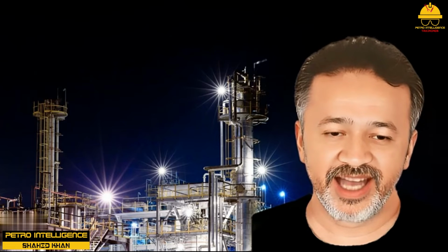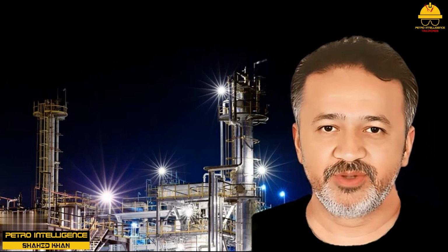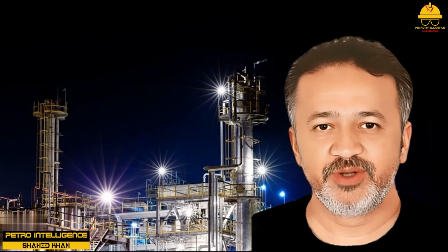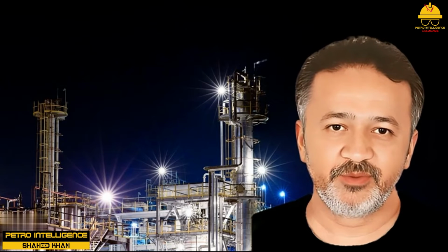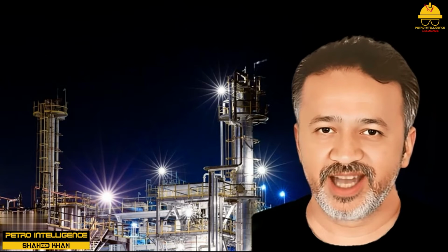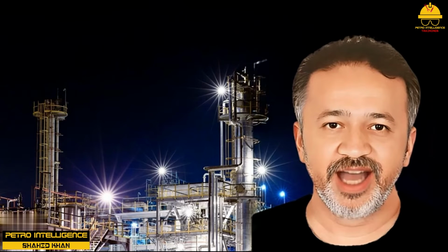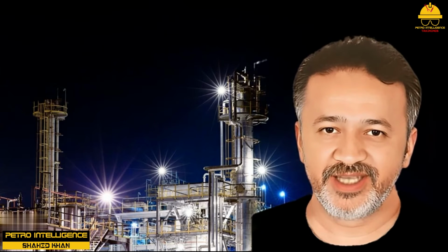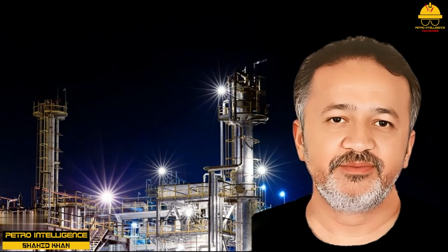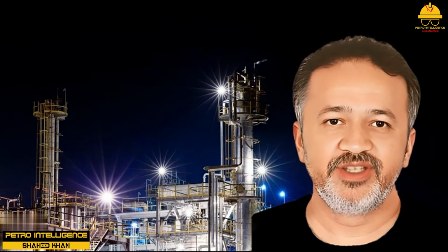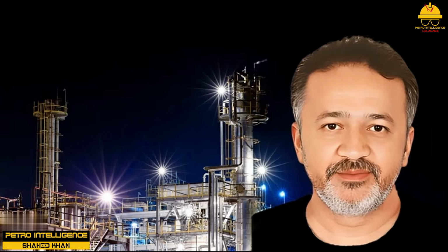Agitation provided by mechanical agitators or by the turbulent flow of the reactants may affect concentration. In general, good mixing or good agitation produces an efficient reaction with the desired products. Poor agitation may produce pockets that have a high concentration of one reactant and low concentration of the other. This uneven distribution may produce undesirable as well as unpredictable products.